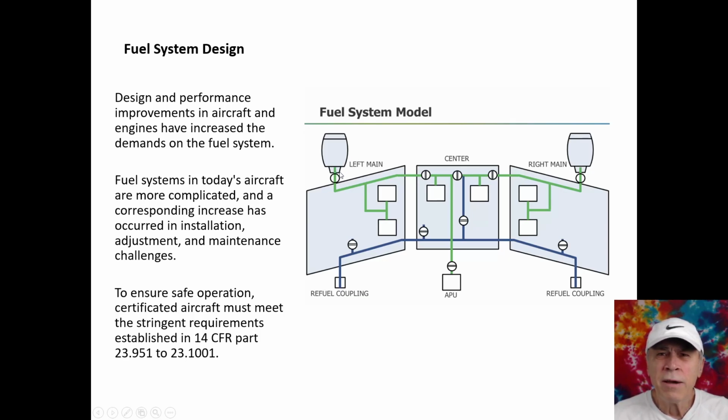And you have various manifolds that are either delivering the fuel to the engines, the green manifold piping type system that is used in effect by all of the white boxes, which are the separate fuel cells or the fuel tanks. And you can see that basically any fuel tank can service any engine, including the smaller APU engine in the back.